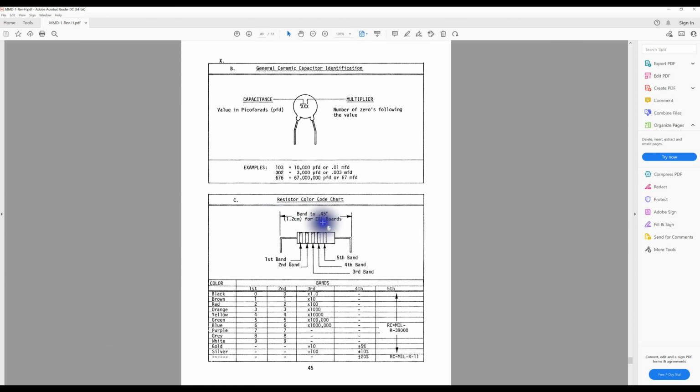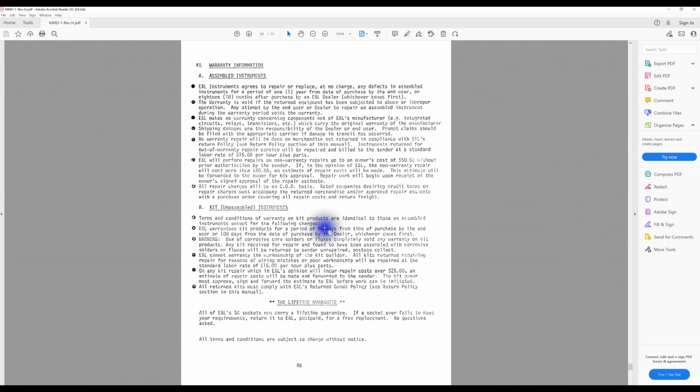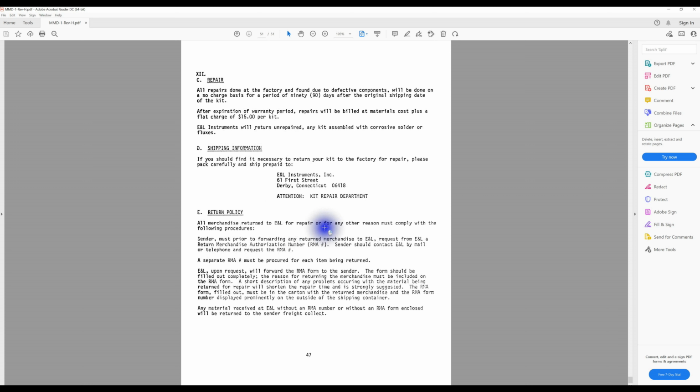Apparently, the resistors are on 0.45 board spacings. That's kind of nice that they told us that. We would be able to have a bender tool so we could bend them to the correct size to drop in.